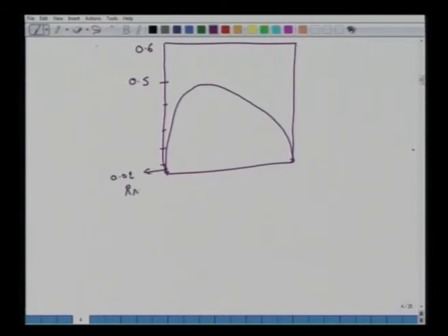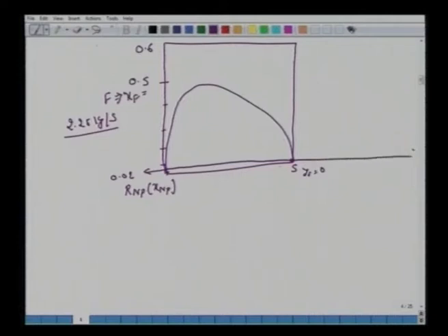Now if we connect these two points, XNP and S, we have a straight line going in this direction. In this case, to find the del min, we find the tie line which, if you extend it, meets this feed concentration. As an exercise, with some trial and error, take this tie line. You will see that this crosses and intersects at 0.48 composition, and when you extend it here, say it meets here, which is del min.